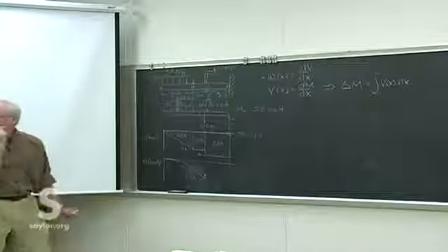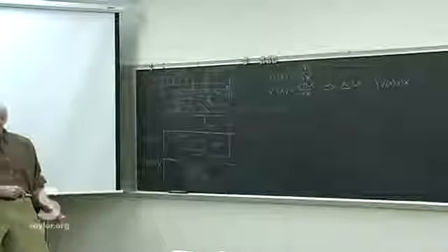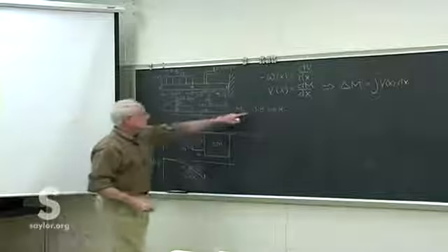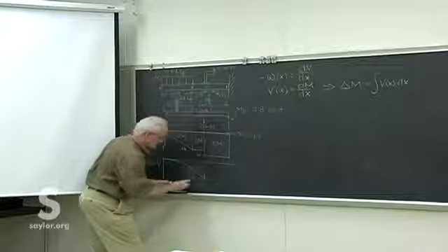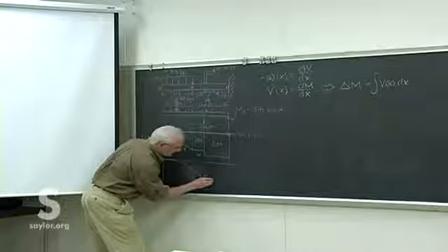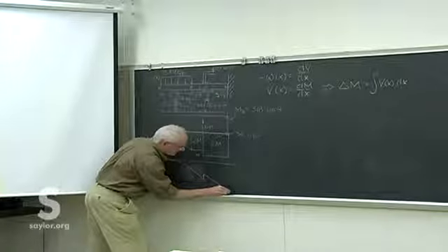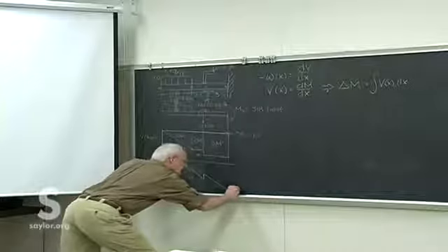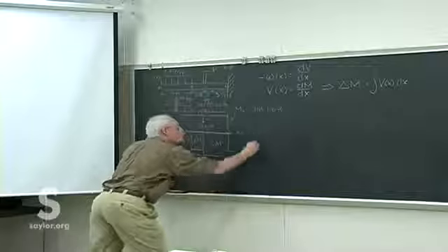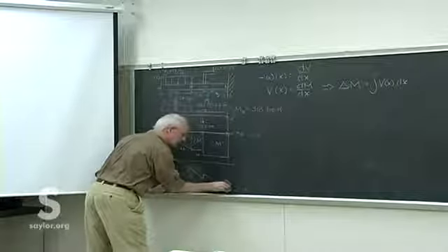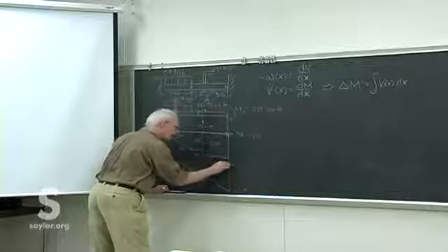So 170 plus 148 is 318, and that's where we expect to finish because we have this applied moment due to this reaction support there. So it takes it down to a minus 318, which is just what we'd expect to get back up to the end of the beam.